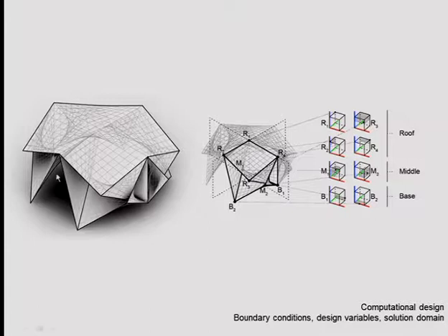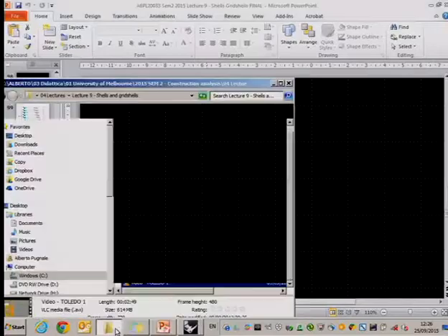So it's possible to make sure that you replicate that in a contemporary way using optimization. So you take 1/4 of the church out of that, and this quarter you make sure that the 8 points of the frame can be moved within a certain domain. And then you calculate the structural behavior so that you get a family of shapes from which you can select. So form finding is, let's say, the way it was designed, and mathematical optimization is a way in which we can design it nowadays. There is no better or worse, but it's just two different ways. And I'm going to show you a video also of that.